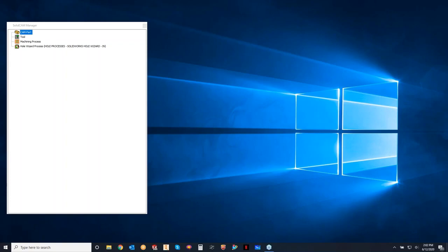It is essentially still SolidCAM minus our integration to SolidWorks. It's just the left menu that you usually see in your window, as a standalone. What you can do with the shop floor editor is open up any pre-existing SolidCAM part file, and you can modify feeds and speeds, you can modify step overs, anything related to the operation, minus choosing new geometry or reselecting or modifying it in the geometry window.